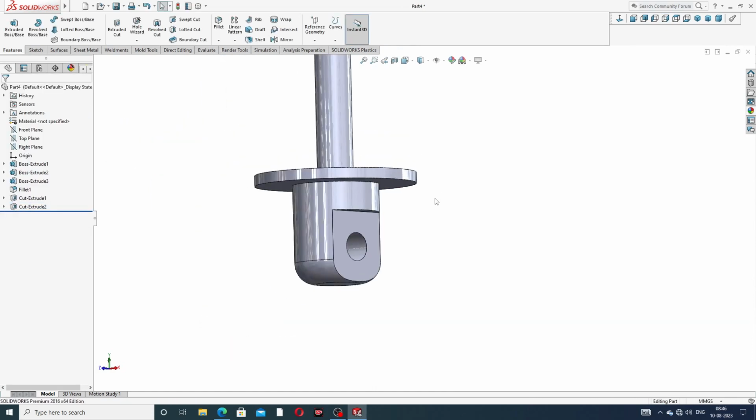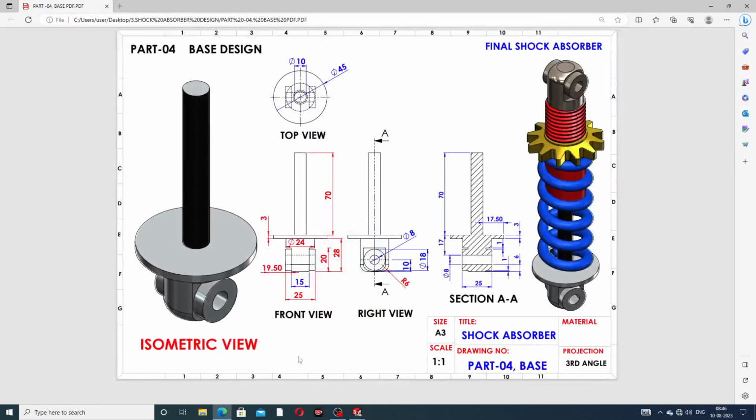Okay, and next is drawing this body. This body is a circle drawn here, 18 millimeter, and the thickness is 25 millimeter, mid plane. This 25 millimeter is the same, the 8 diameter is the same here, this length is also the same, and the thickness is also perfect, and all of it is not mentioned here.